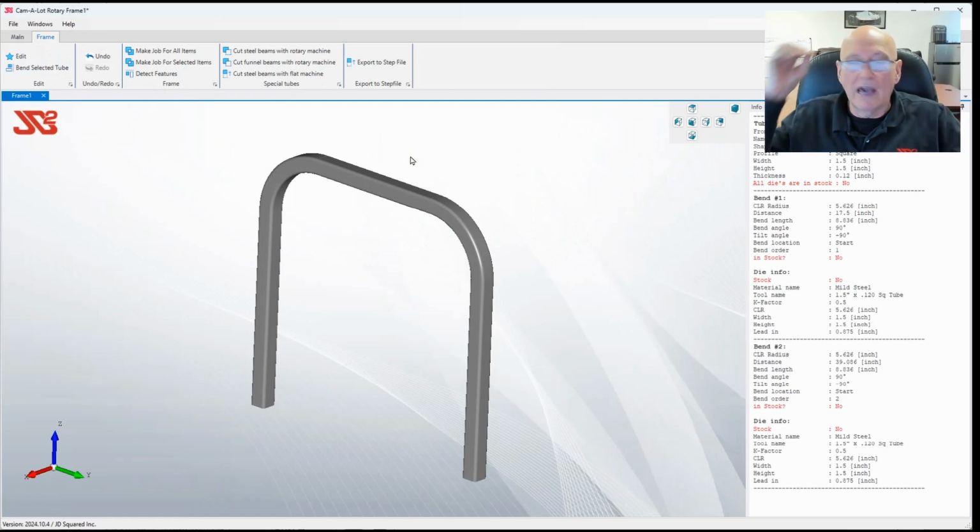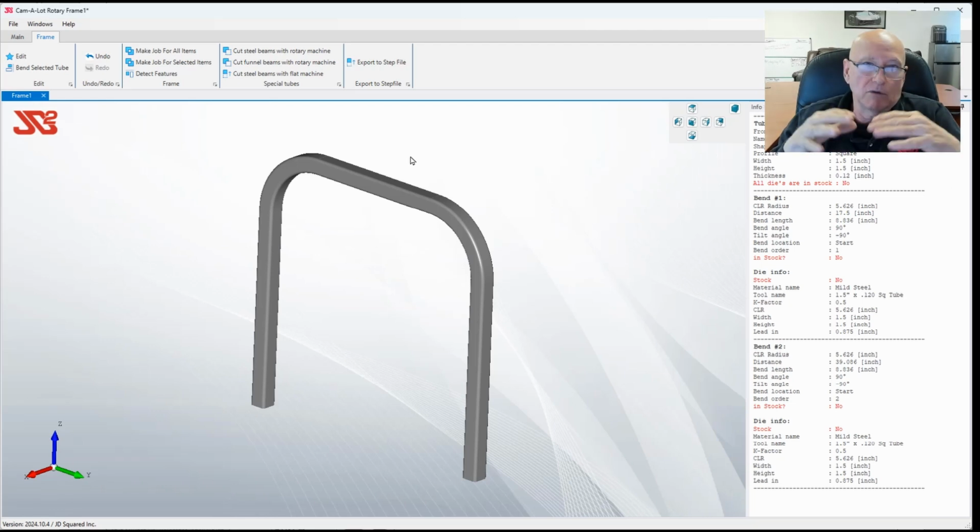The decision has to do with different bending machines. Some companies have different benders, like our presses out there that we use for the sheet metal to make our machine. We have two different high precision presses that produce different bends for the exact same K factor and the exact same material. The reason that happens is the tooling of the part that's actually making the bend is slightly different. So we're also going to have a slightly different radius of the finished sheet metal bend.